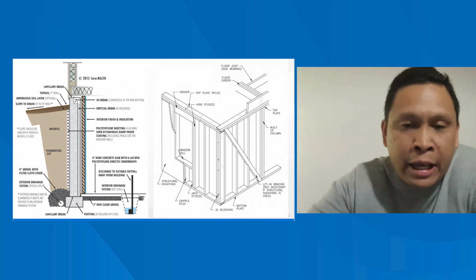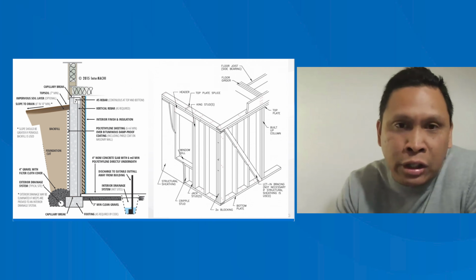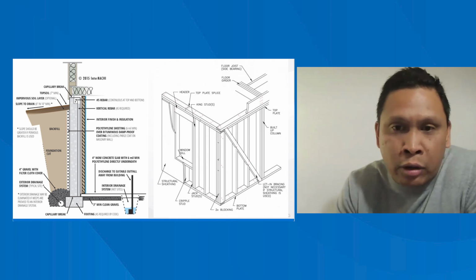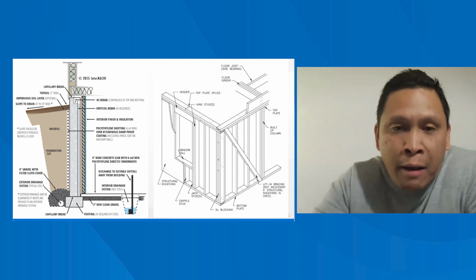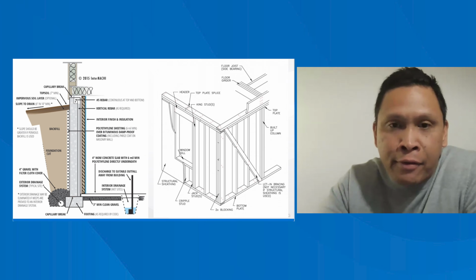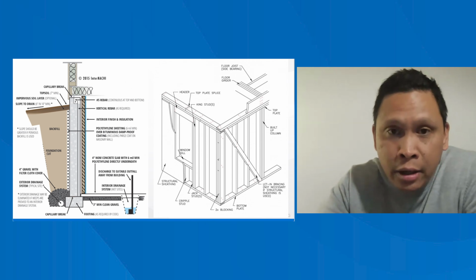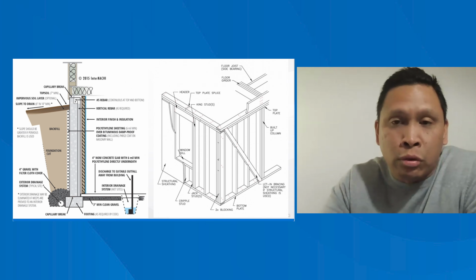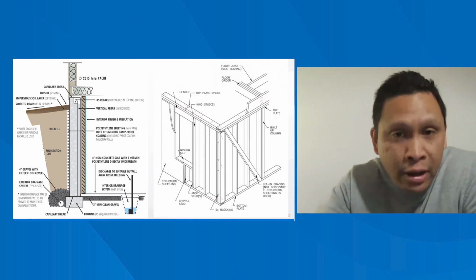Foundations and managing moisture are two conditions that will pop up on almost every single inspection, especially when it comes to resales. When we're not managing and controlling the moisture as much as we can, what's going to naturally end up happening is you're going to have conditions where water is transitioning into the home. You're going to have conditions where the foundation will start to crack. You can have conditions where the foundation will start to move. And then it creates hosts of other issues inside the home.